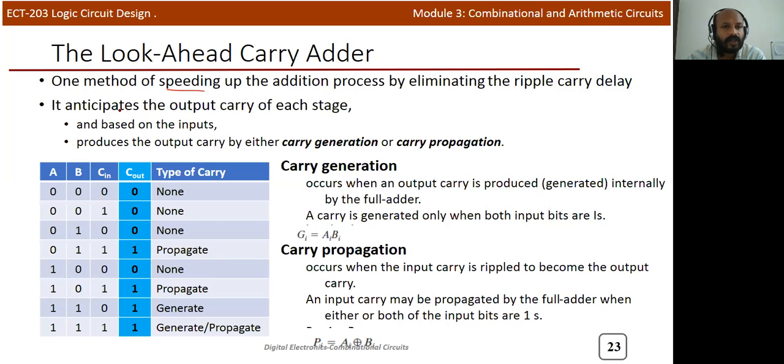propagation delay. So in look ahead carry adder, we will predict the output carry, or we are anticipating the output carry of each stage by using its inputs. Okay, so this is the concept behind look ahead carry. Instead of waiting for the previous n-1 stages, we are predicting the carry by using some other concept. So for that, we are using two terms, carry generation and carry propagation.